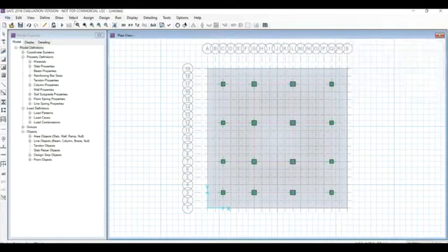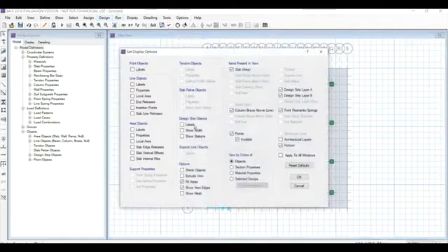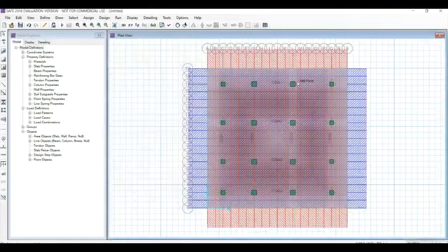To see the strip layers, let's go for point of view and then go for set display options, labels, show width and show signature, and okay. These are all the strip layers we have drawn.